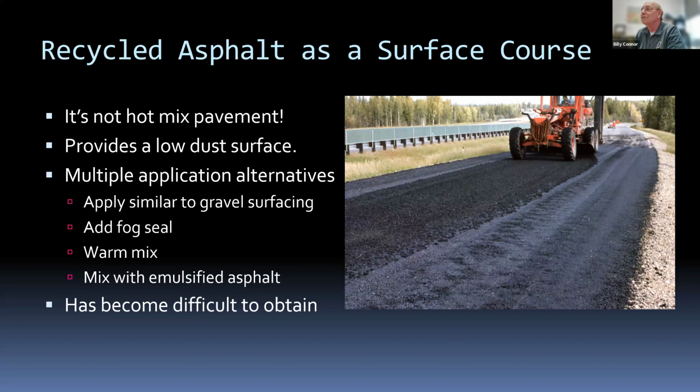My driveway is made with recycled asphalt, and all they did is treat it like gravel, basically. Put it down, roll it, spread it out, and then compact it, and it will hold up for quite some time. My driveway is about 6 years old now, with that surfacing material, no dust, and it's really kind of nice to be able to be out there and working around the yard without dust coming off of my driveway.